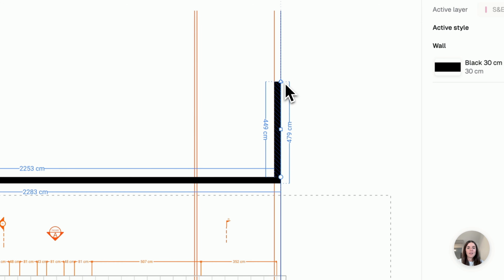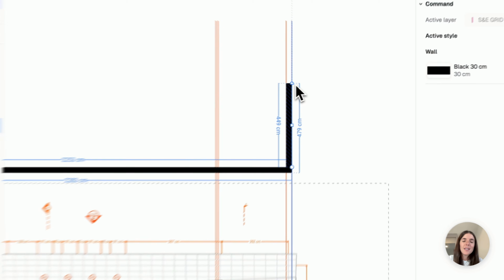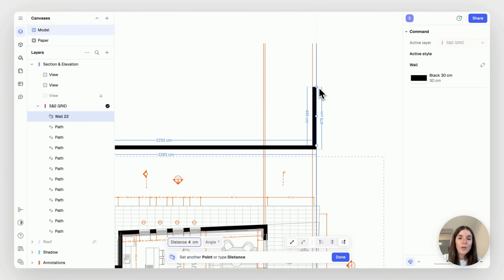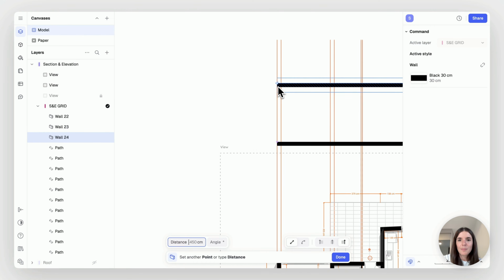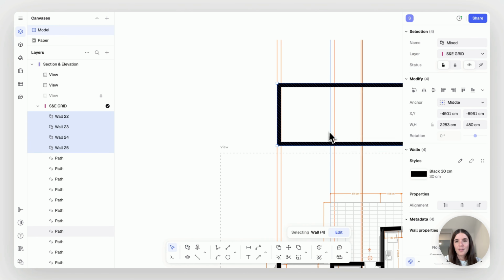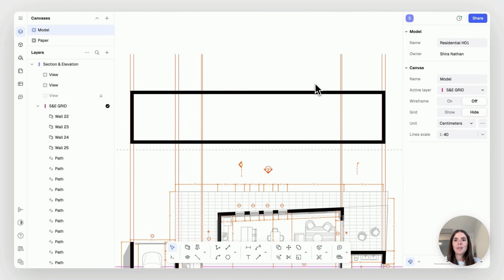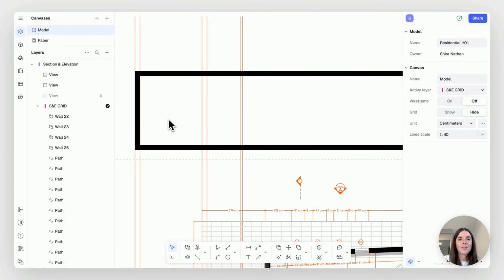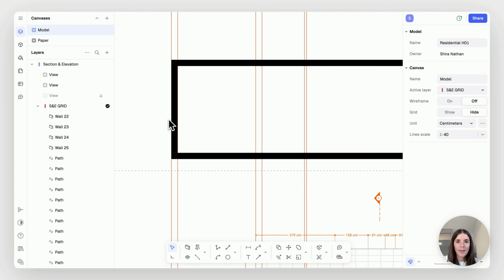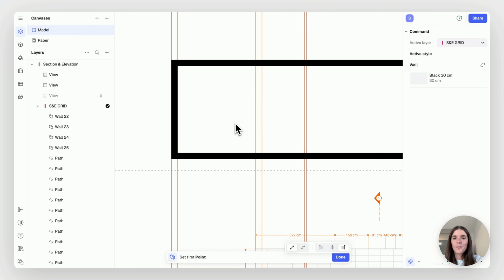The height of my project is 4.5 meters, so it's a nice tall ceiling. You can see that I'm entering the distance at the bottom, so I'm working in centimeters, so I'm going to do 450 centimeters. Place that. Place my wall here and start off with this kind of rectangle. This is going to be massaged and worked. We have different heights in some areas of the floor plan. You'll see that soon, but I'm just starting off by drawing this and making everything super clear for me.